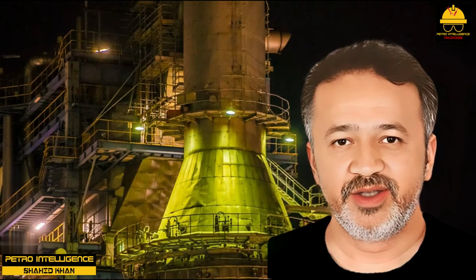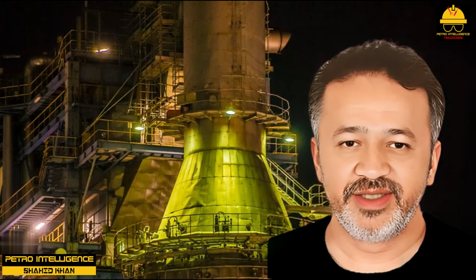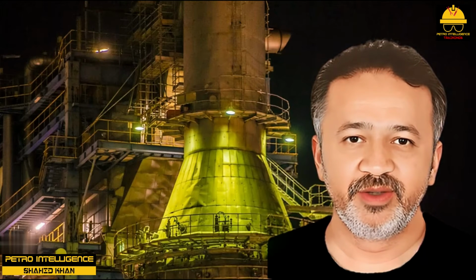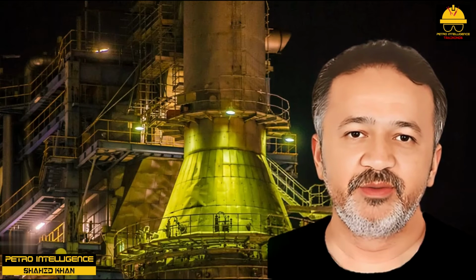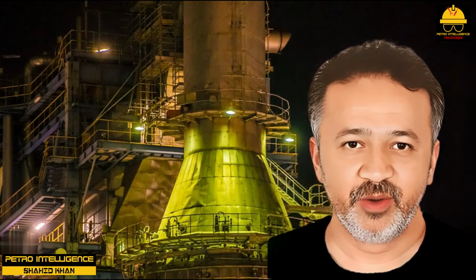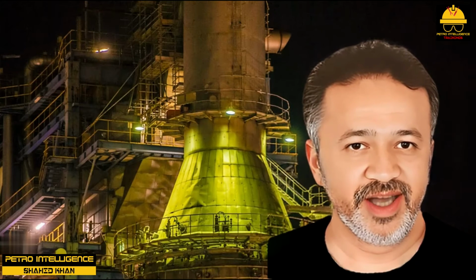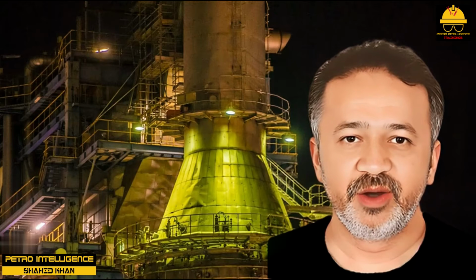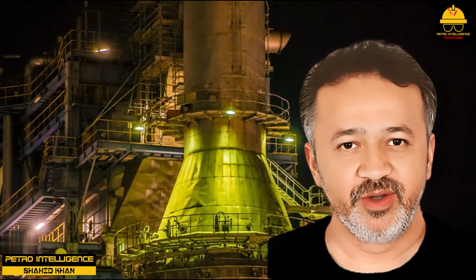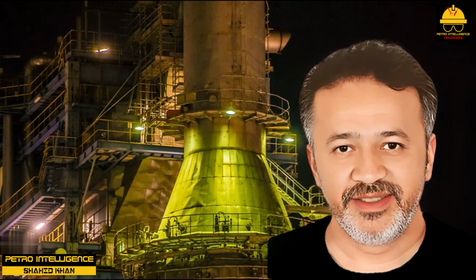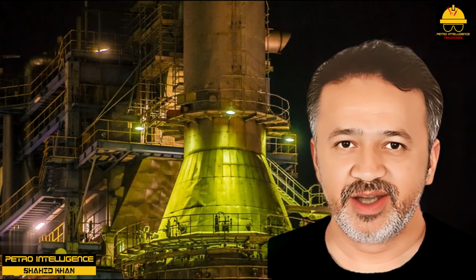The outside operator, Operator B, went to check on the firebox and, seeing that it was full of long, licking, yellow, smoky flames and had taken on a very hazy appearance, reported back to Operator A that he considered the amount of air in the firebox insufficient. Meanwhile, Operator A looked again at his O2 analyzer output, which showed 7.5% O2. He told Operator B that there was plenty of oxygen because the analyzer showed 7.5% O2, so he must be mistaken and, in fact, that he needed to go and pinch back still further on the air register to cut back the combustion air.